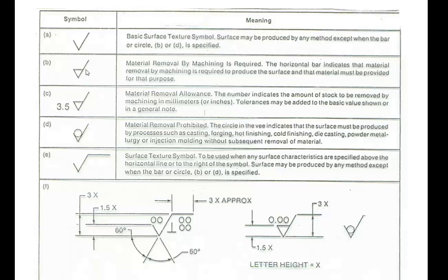Okay, if the finishing process is material cutting, then in some cases it may be necessary to specify the material removal order. The number written over here in this example, 3.5, is to say that there should be extra material before the finishing process, and via cutting the material from the starting surface to the finishing surface, 3.5 millimeters maximum, satisfy the surface quality requirement.